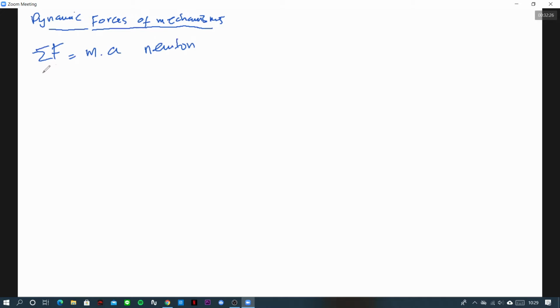And then the method we are using, the second law of Newton, and also Euler moment, which is sigma moment equal to I times alpha. We call it Euler moment, because Newton proposed it only for linear motion. So this combination, we call it the Newton-Euler method.